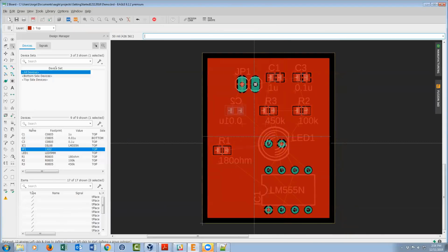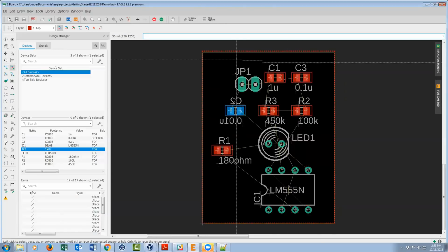Now, visibly, this can be a little jarring because when you start to route, it doesn't automatically update because that takes up a lot of resources on a big board. So what you can do is if you just want to undo the fill, you go to rip up and you have rip up polygons. And it'll put it back to AirWire form. To fill it in, you just click Rat's Nest. So Rat's Nest fills it, rip up polygons unfills it. Rat's Nest also recalculates the AirWires so that they're straight lines, shortest distance straight lines.